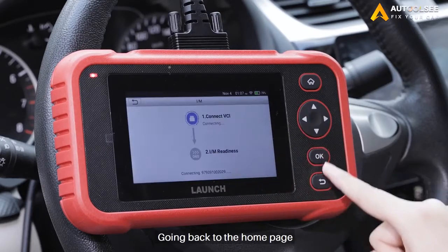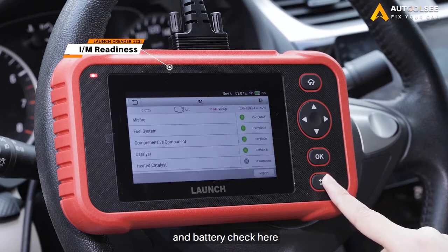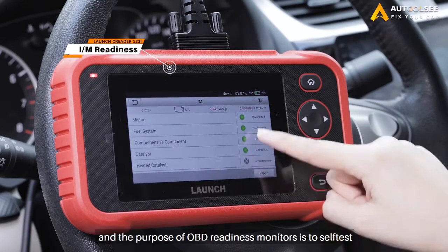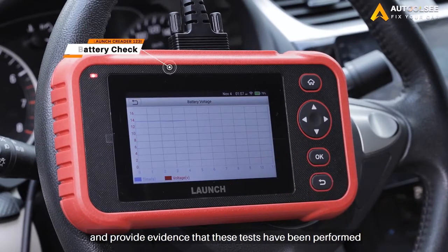Okay, going back to the home page, you can see that there is a shortcut for I/M readiness and battery check here. And the purpose of OBD readiness monitors is to self-test the vehicle's emission systems and provide evidence these tests have been performed.